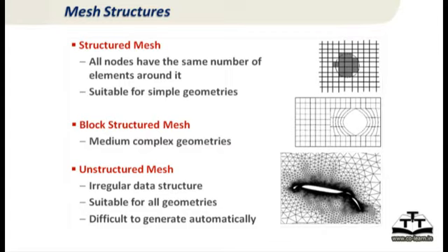But what people forget is that the mesh generation itself can give you a lot of headache. Creating a structured mesh is automatic and fast. Creating an unstructured mesh is highly interactive, can take a lot of time, and can introduce a lot of errors in the process. So you have to be careful about the gain and loss from structured and unstructured meshes.